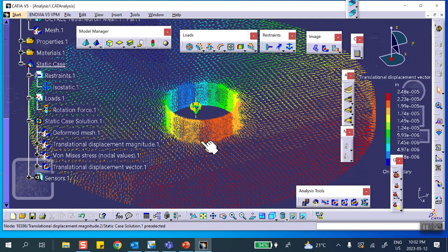But the circular rings of displacement are not displacement in x, y, z. It's the displacement in the radial direction. So not that this is wrong, it's just that I don't want to see the patterns of displacement as XYZ coordinates in the XYZ coordinate system. I want to see it in the R theta Z coordinate system.